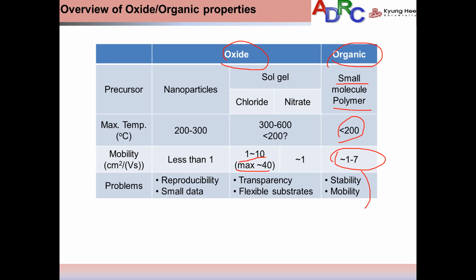But the main difference is in the case of what is called the sol-gel process. The sol-gel process means that you are using precursors which will interact in the solution, and then you will print the solution and another material will be formed. So you use a zinc precursor with a tin precursor, for example, and you mix them in a solvent.